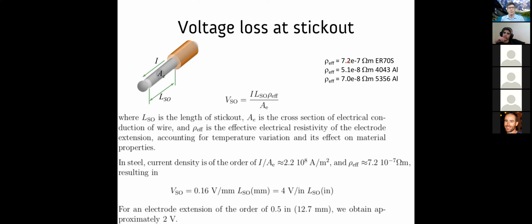Resistivity is higher with more alloying elements, because conducting electricity, the flow of electrons gets disrupted with all these different atoms in there. And so if you were to measure the resistivity of a base plate, say a 1020 steel or whatever it is, you'd measure a number. If you measure the resistivity of the wire you used to weld that, the resistivity is higher because the wire has more alloying elements, right?